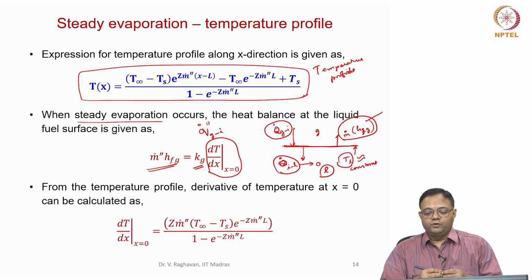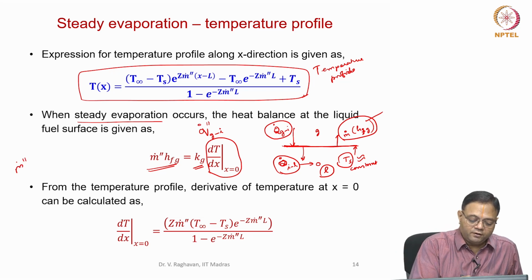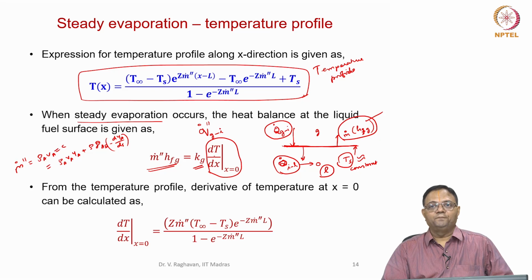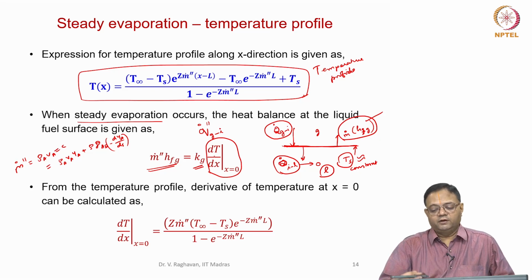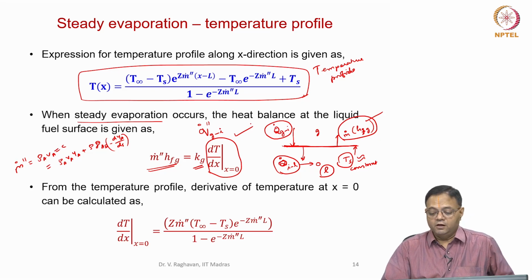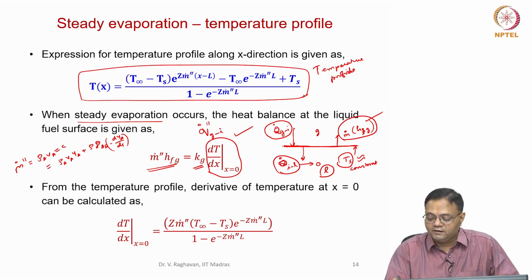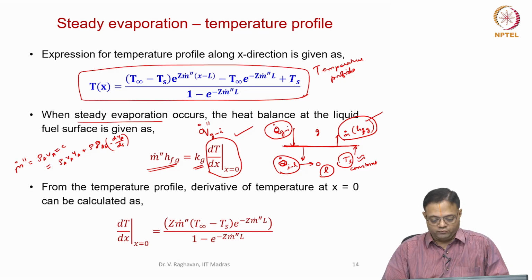We have seen the Fick's law. This mass flux equal to rho A Va is constant, which is equal to rho A Va Ya plus rho Dab dYa by dx. So, this is the mass transfer statement, this is the heat transfer statement. Okay. So, for the heat transfer based analysis, I use this condition, which is the interface condition for the energy balance. Why? Please understand that the liquid phase heating is now absent because Ts has reached a constant value, almost constant value.